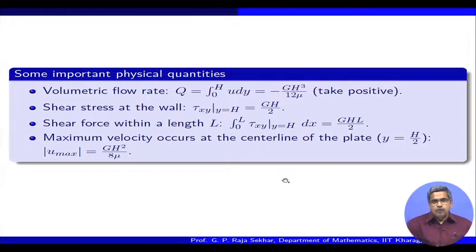Okay. So far we discussed very simple cases. We did not really appreciate how the Navier-Stokes equation gets reduced into such a simple form, because it is unidirectional. So, the left hand side is 0 and then y momentum is almost gone, etcetera, etcetera. Okay. Now, let us move on to a curvilinear coordinate system, say a very simple cylindrical system, then see how the Navier-Stokes equations really reduce under particular assumptions.